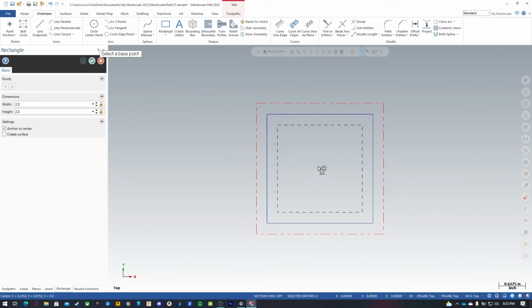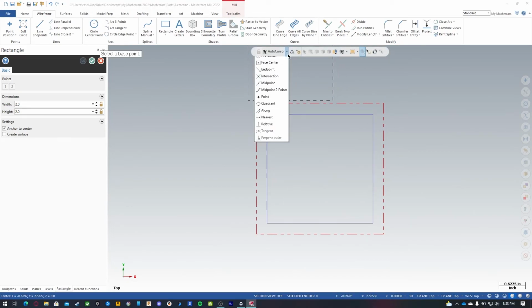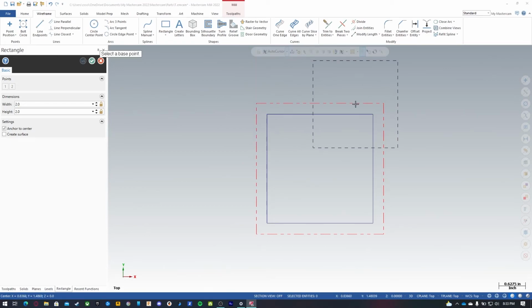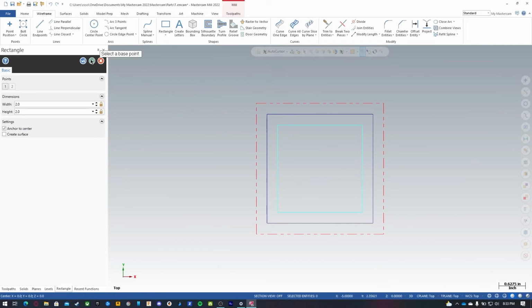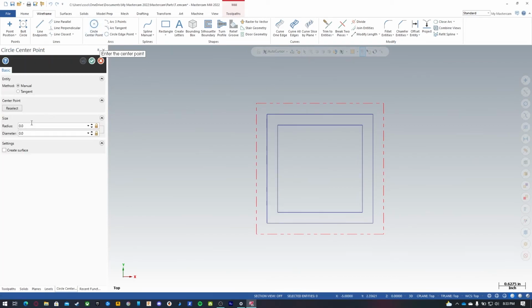Now let's make another box where we can specify our hole positions. And we'll set this at origin again. And once again, press O. And it'll link to the origin. So now we're going to specify our hole diameters at 1/4 inch, and we're going to lock them. So then we can just click on each corner, and it'll maintain the same size.